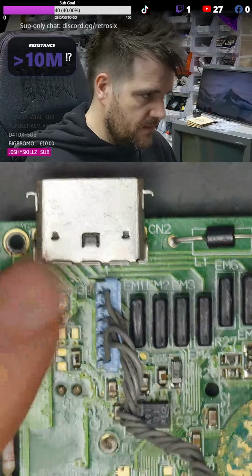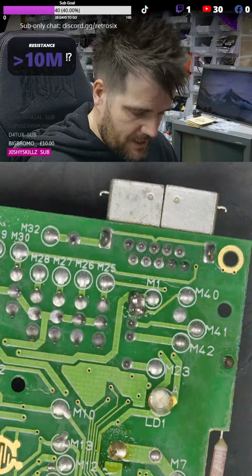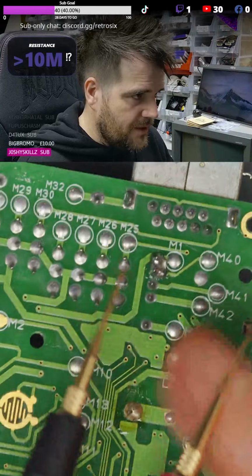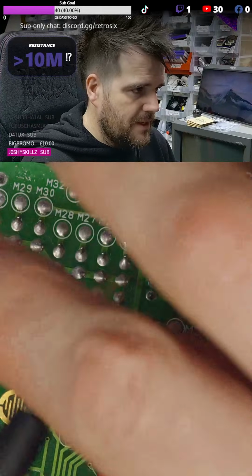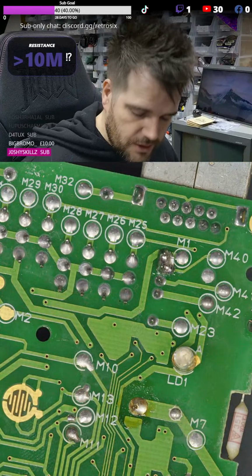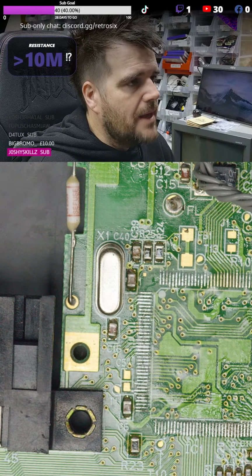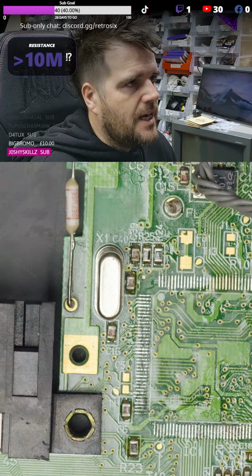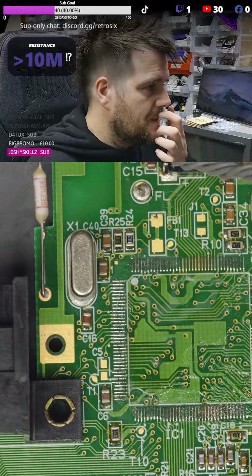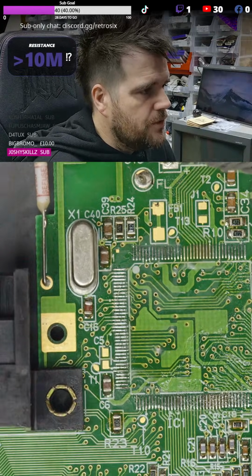But really, that got us no closer than the thermal. So it's a method I rarely use, just because even when you're talking low ohms, even a bit of dirt on the probes or board can drastically affect that reading. So really, the only methods that you can really use are the resistance, the IPA, the thermal, the bench, and I guess the low resistance is the extra mode.